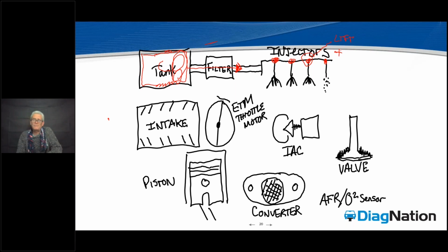So I'm going to add fuel, okay? Now, let's remember we've got varnish deposits working on these injectors, and then let's concentrate on good injector spray versus fouled injector spray. This is another area that we can't physically see as the engine's running that becomes critical to consider.